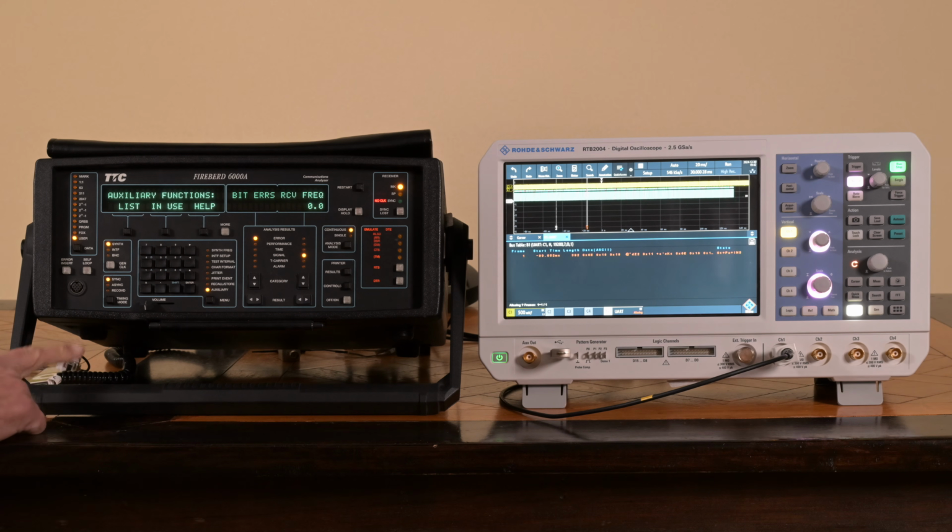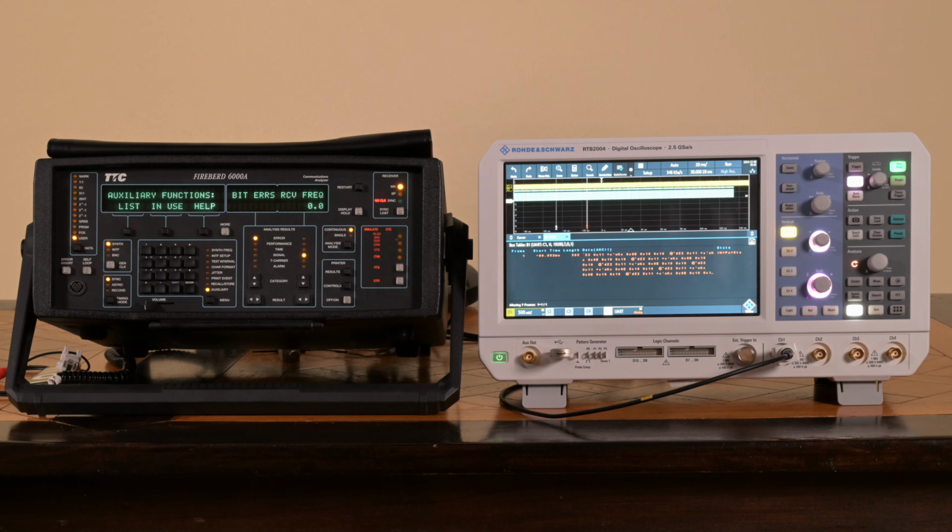One of the other things that the device can do is also create asynchronous types of messages. That means a message where you have a predefined format with a number of data bits, a start and a stop, etc. Like the regular type of data that goes over a serial bus, like RS-232 or UART, as it is commonly called on oscilloscopes. And to do this, you set it on async and you make sure that all the other settings match in terms of the data length, 7, 8, 9 bits.